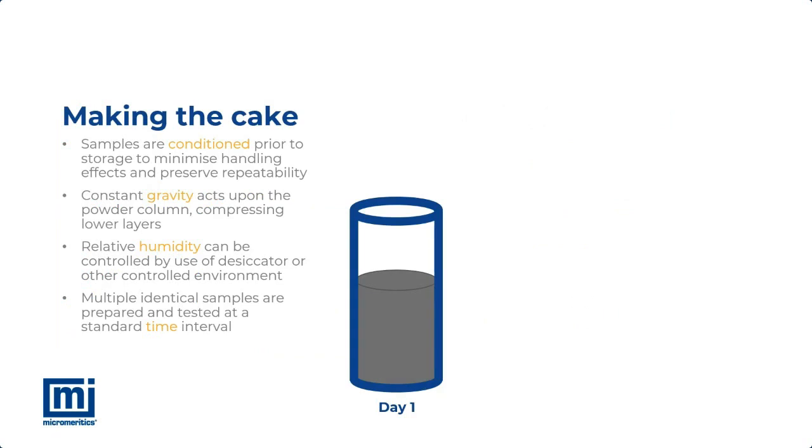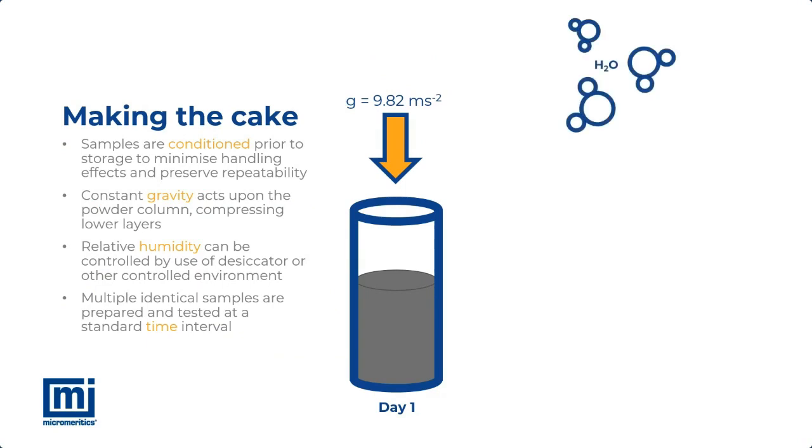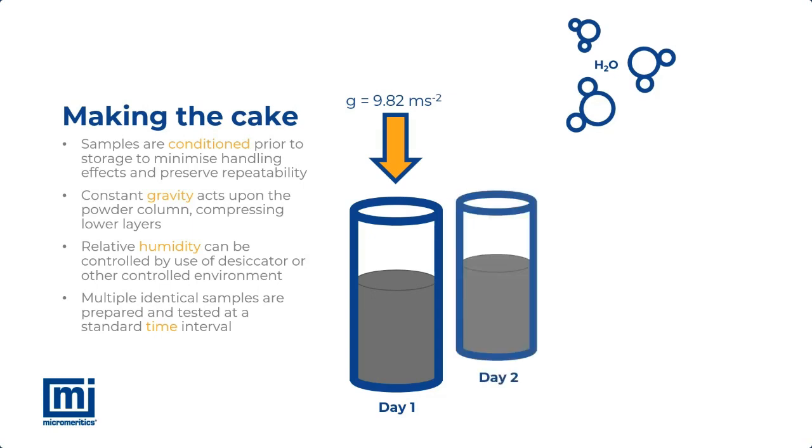This tends to be a roughly exponential increase and describes a fairly smooth curve. For the experiments performed in this study, samples were conditioned by using the blade to break up any loose agglomerates or air pockets and to leave the powders in a loose, homogeneous packing state. This ensures that testing is reliable and repeatable, and that any operator influence is minimized.